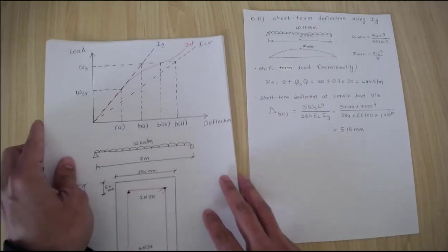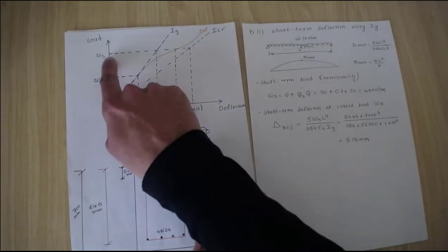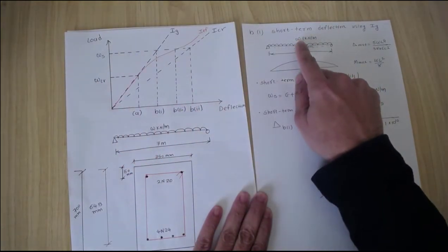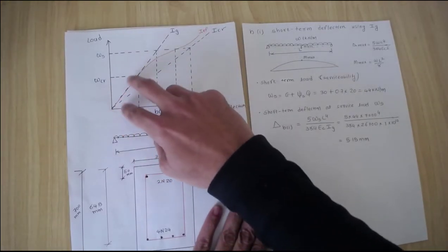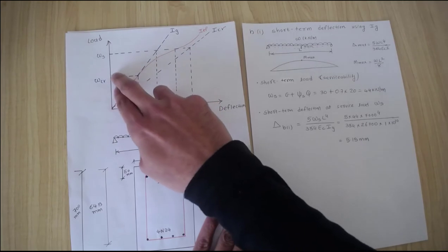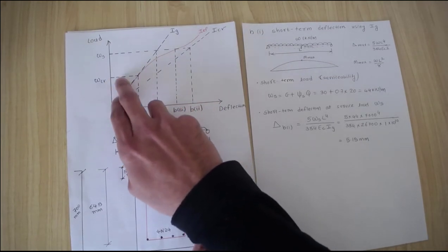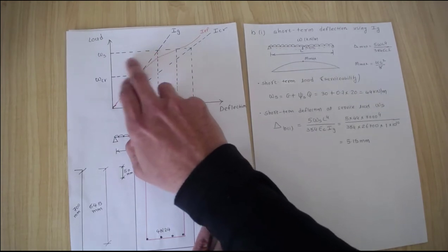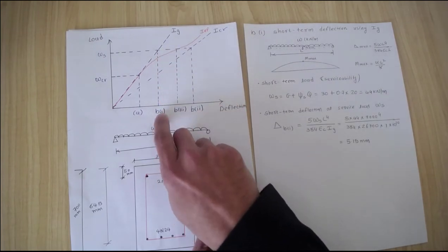Now in these examples, we say that the beam is loaded up to serviceability load. So the load coming onto this beam is not the load which allows this kind of theoretical concept. We are just finding the point where it's going to start cracking. So that point we found. Now we say that the beam will be loaded to the serviceability load, which is WS. At this particular point, what would be the deflections that we want to find?